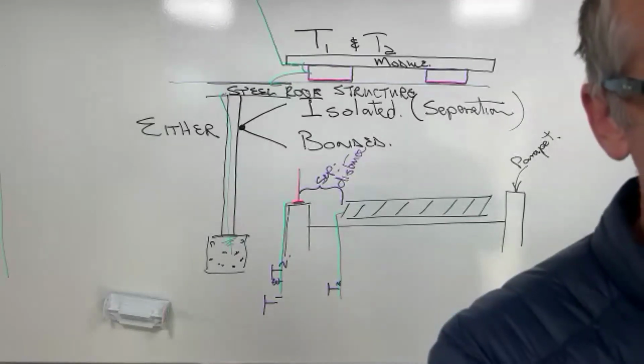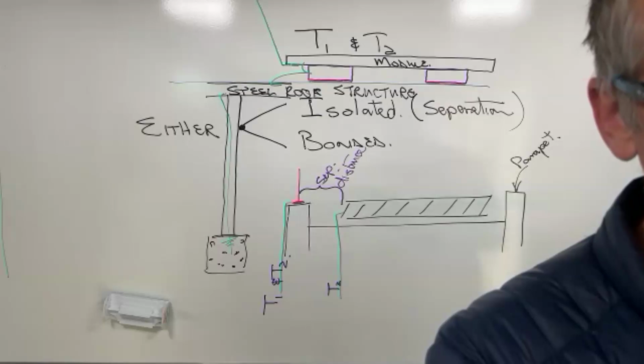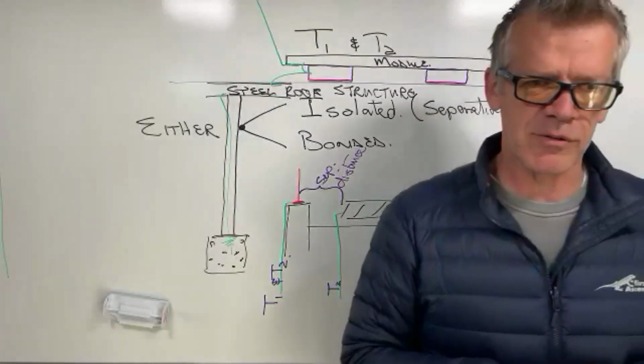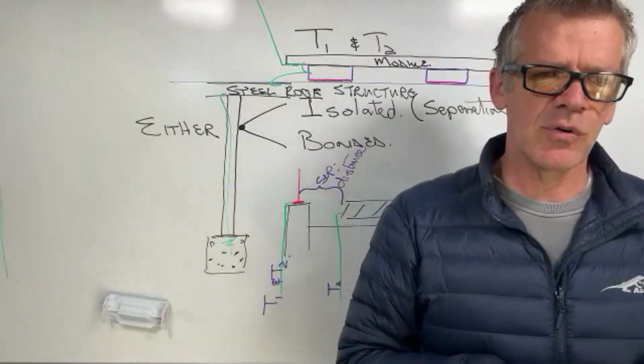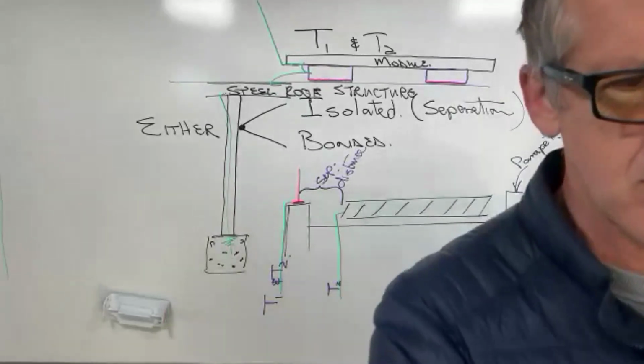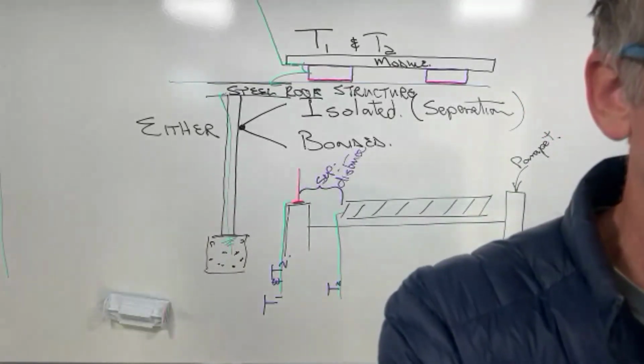Also, for me, the interesting thing about copper bonding strip is aluminium. Aluminium doesn't like copper very much. So you shouldn't bond copper and aluminium directly to one another, because you're going to get bimetallic corrosion.